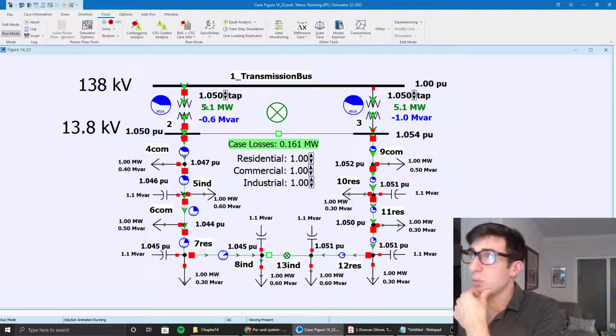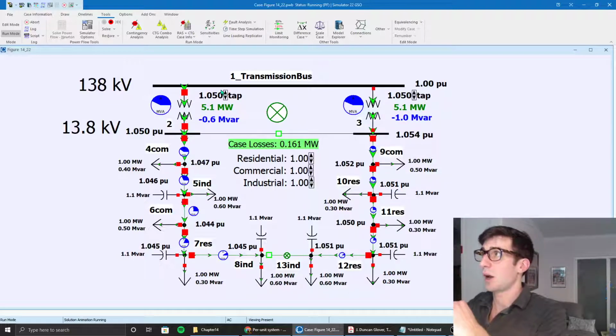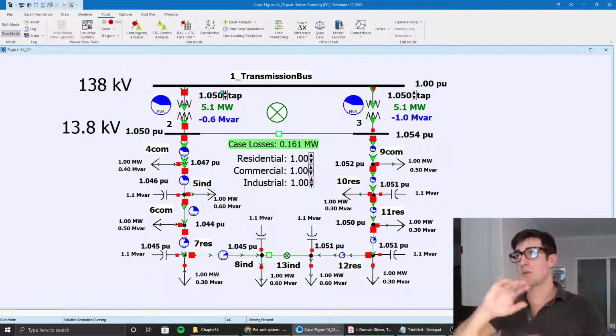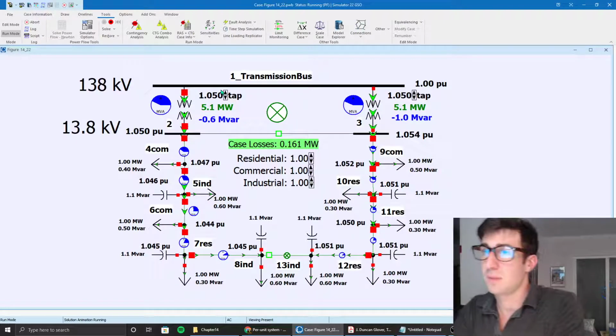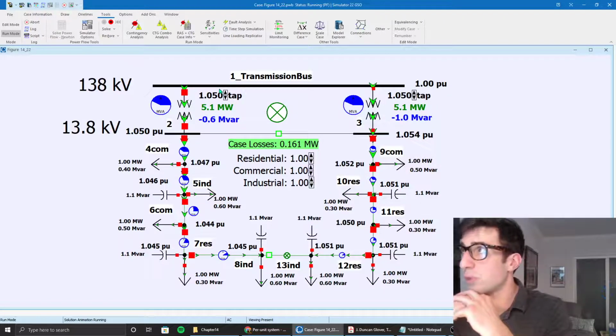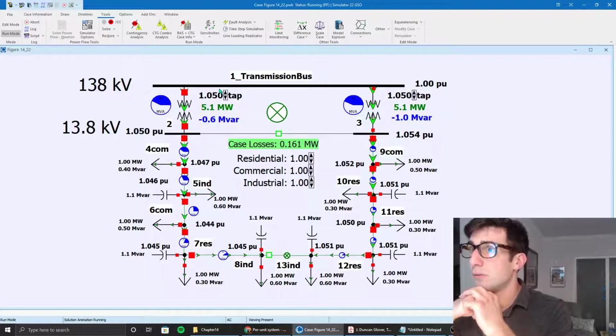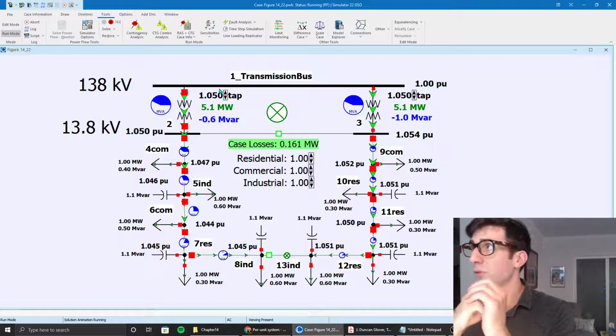And we're tapping. We have a function to tap into this 138 kilovolt transformer. So a tap is basically you're tapping up or tapping down. They're physically switches, and it's moving the conductor within the transformer to select how much voltage you're drawing out of that transformer.